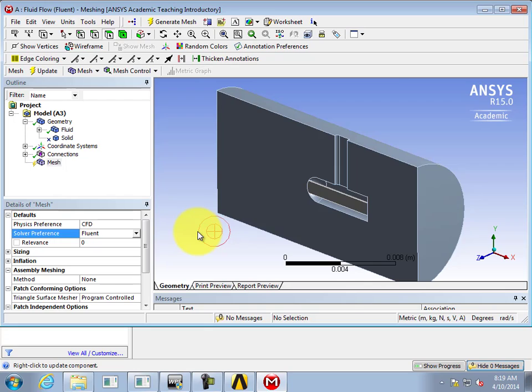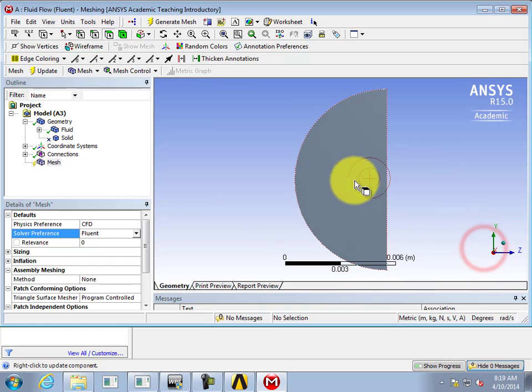All right, but once we get into Fluent, it's going to be really helpful if we have some of the surfaces and different parts of our model labeled in such a way that we can easily pick them out and apply our boundary conditions. So that's what we're going to do now. If we change our axis, I can click on my triad here. So here's the positive X. Let me go to the negative X and click on that so it quickly spins around to that face. Go ahead and click on that face so it turns green. Everybody good there?